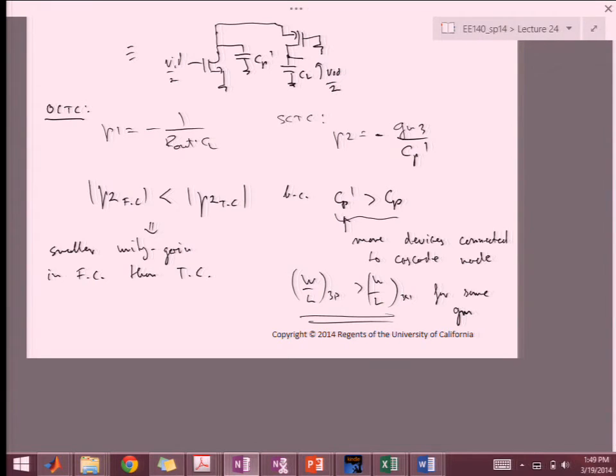Now, we said that adding a current mirror to turn this into single-ended designs, like the designs I showed you last lecture. You need to add a current mirror, which adds a pole and a 0 at omega t over 2 and omega t, right?